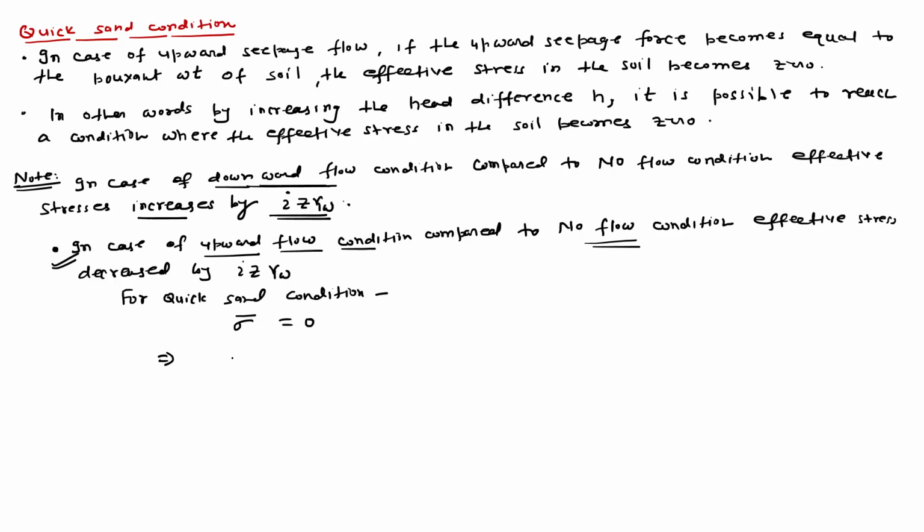In no flow condition, effective stress is total stress minus pore water pressure, and this effective stress is decreased by i critical z gamma w, and this will be 0.